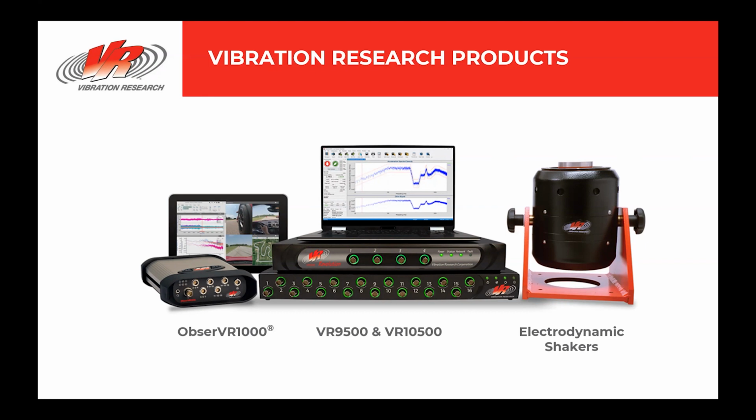It is scalable to 512 channels, and its features include a sample rate of up to 256 kilohertz and 4 outputs for multi-shaker testing. Vibration research controllers have a high-speed RISC processor that can process large data sets and efficiently run vibration tests at low and high sample rates. They are compatible with all electrodynamic and servo-hydraulic shakers. The VR9500 and VR10500 also function as data acquisition devices.